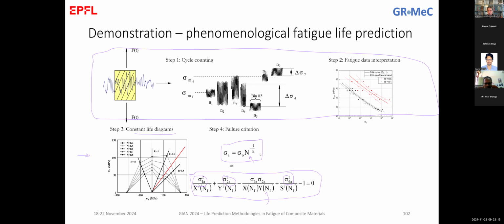And as we said before, the final damage criterion that is used, the damage summation, is the linear damage according to Miner's rule, which says, as we described before, that the partial damage of any loading is the ratio between the number of cycles that we apply at this loading over the number of cycles that the material would fail if this loading were applied continuously.